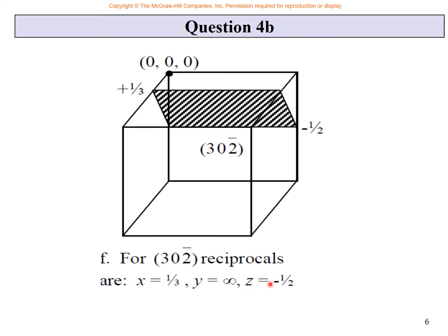As soon as it is z minus half, remember, you move the origin from the origin to the end of the z axis. This is the standard technique: if any of the Miller indices is negative, then on that axis move the origin. Because there is only one negative number, which is on the z axis, your original origin was here, this is x, this is y, this is z, so you move the origin from here to there, so that now you can easily find the negative numbers. Otherwise from here you cannot find the negative, it will be outside the box. So now it is there.